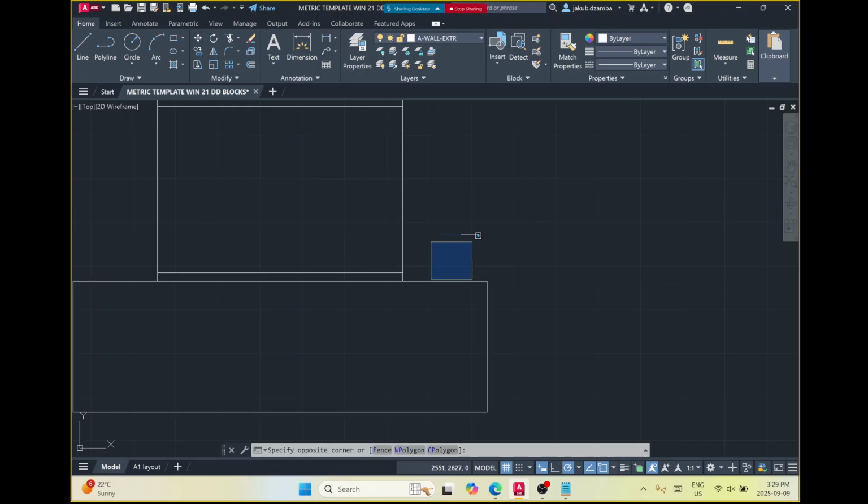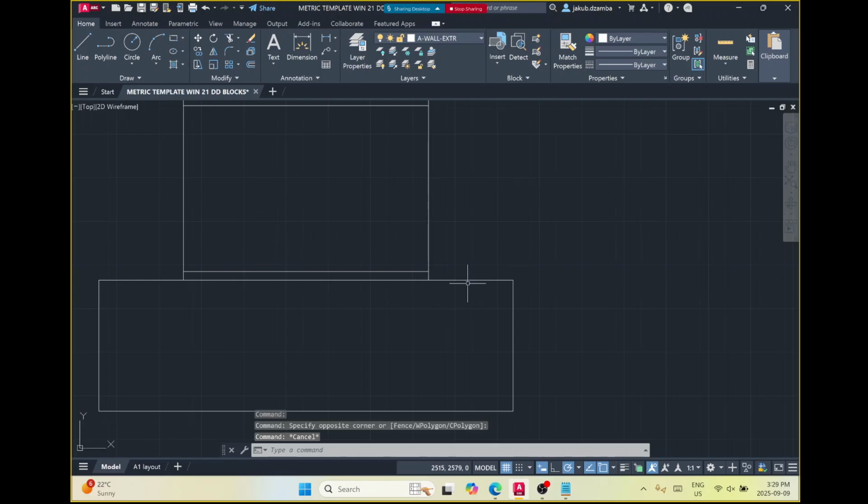And now we need to start offsetting the lines of this rectangle, but we can't really offset it because it's a rectangle, so we need to break it apart into lines. So this is probably the coolest sounding command in AutoCAD. We're going to type in explode and click on the rectangle and hit enter, and it should work. Oh, it didn't. Hold on. Explode. Maybe select the rectangle first and type in explode, and then it should break into individual pieces. Did that work out?